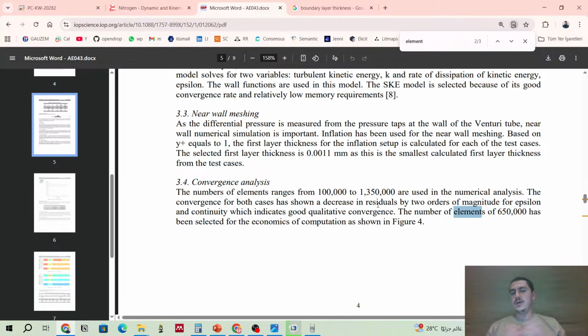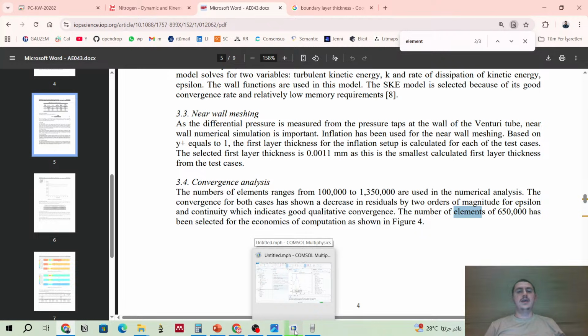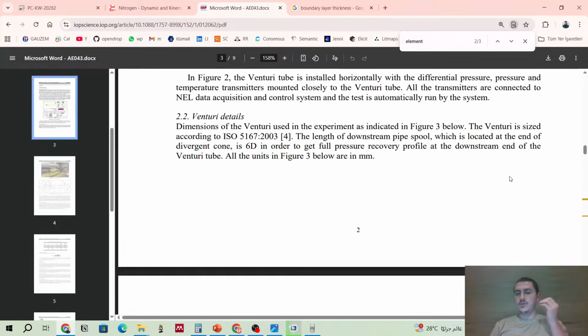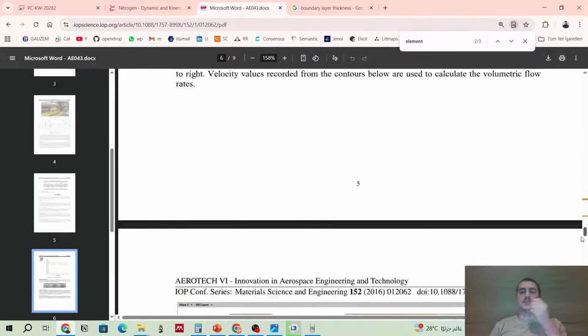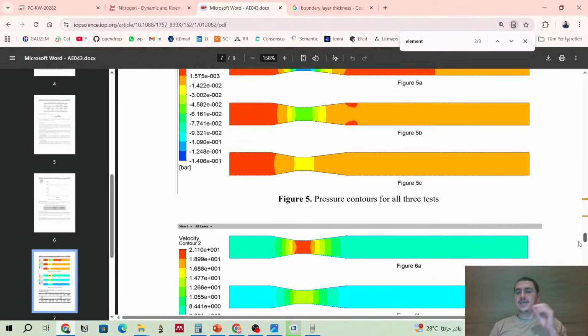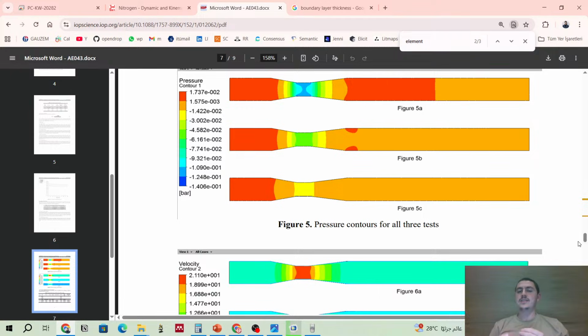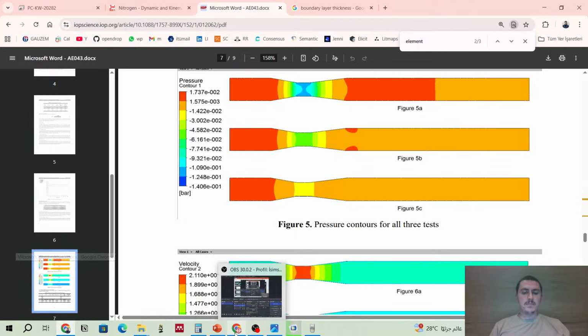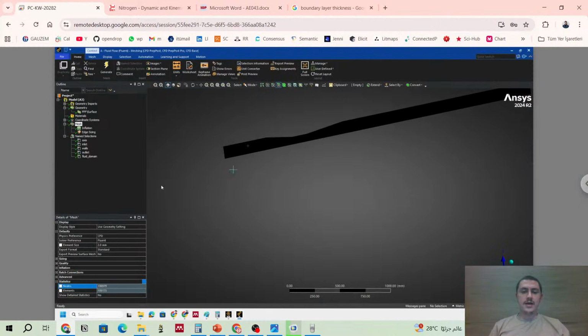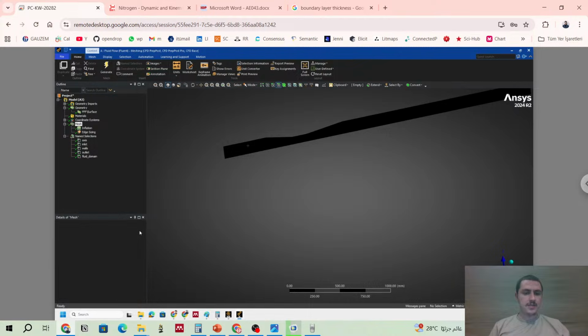So you understand the paper authors actually spent a lot of time on this simulation work, and we want to take a good, well-designed paper, read it, see the results, and quickly reproduce some of the ideas. We reproduce the geometry, we try to mesh. We also try to solve the physics to get convergence, but step by step: if we have trouble in meshing, we can go back and mesh again. But now, I just want to check skewness and some quality indicators.